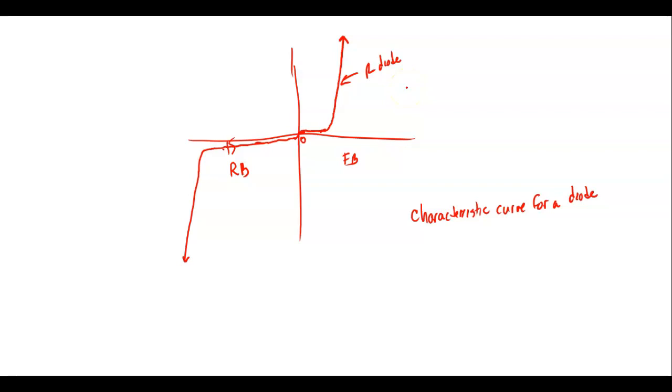So everything's got a little bit of resistance, and if you put more current through it, so we use approximately 7/10 of a volt, but that's an approximation, right? The more current you put through it, it'll drop a little bit above that, and the less you drop, it might even go a little bit below. That information is some of the information in the data sheet.